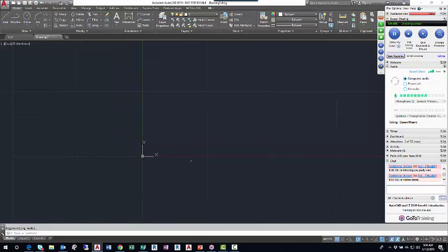Right now, where this icon is sitting, it's at a coordinate called 0, 0, or 0x and 0y. The drawing window is divided into coordinates that are x related horizontally and y related vertically. You can even see that on your UCS icon. Pointing to the right horizontally is x, pointing up the screen vertically is y. That's a typical default setting for an AutoCAD drawing.